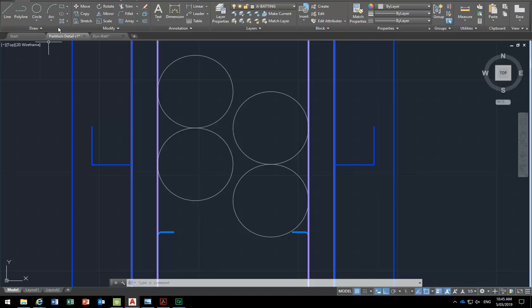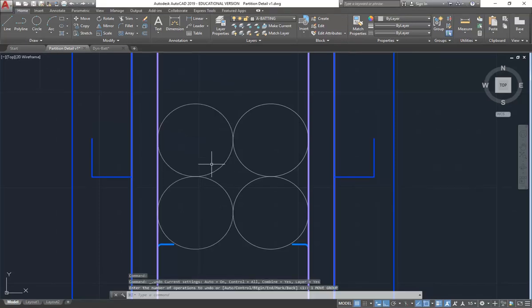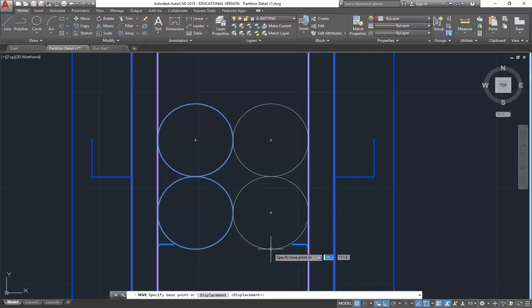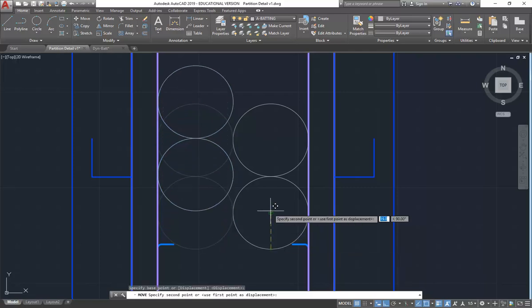Yeah, oh no, I did it by snapping. So I'll do that again. I selected the two on the left, then click to move, and then picked it up on the bottom, on say the quadrant, and then snapped to the radius, and that makes it halfway. Snap to the centre, so not the radius.